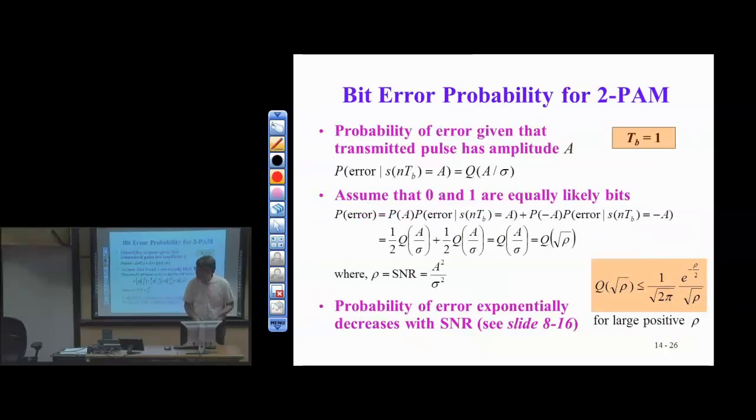Okay, I'm going to wrap things up with this slide, so just hang on. Now consider the other case, where I send an amplitude of capital A and make a mistake. If I threshold against 0, I'm expecting a positive number. But if I get a negative number, I've made a mistake, and it turns out it's the same probability of making a mistake. It's the tail, but the negative tail in that normalized distribution.